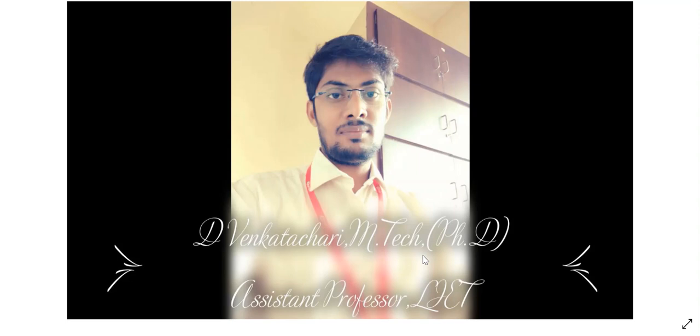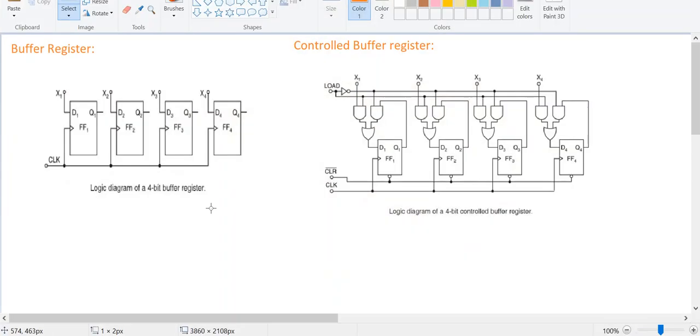In this video lecture, I would like to discuss the concept of buffer register and control buffer register. So let us have a look at the circuit diagram. This is our buffer register circuit diagram. In this buffer register circuit diagram, I simply use 4 D flip-flops. A buffer register can be used for storing information, or else we can load the information. So we can use the D flip-flop for this particular purpose. Here we can store 4 bits of information in this buffer register.